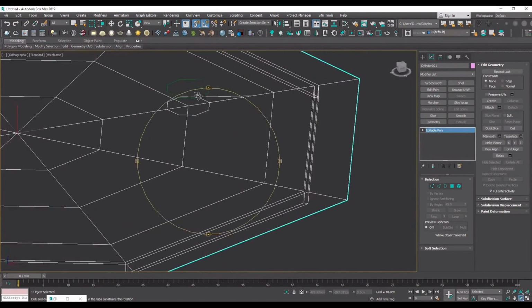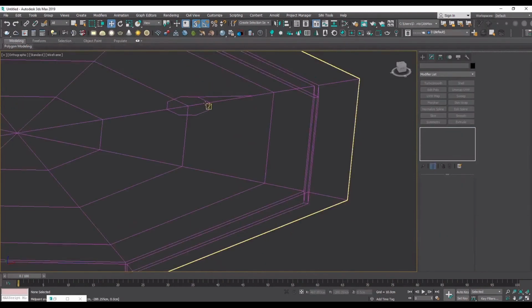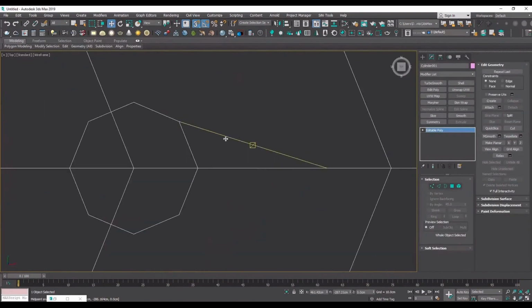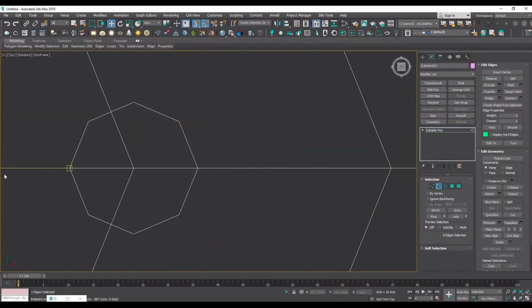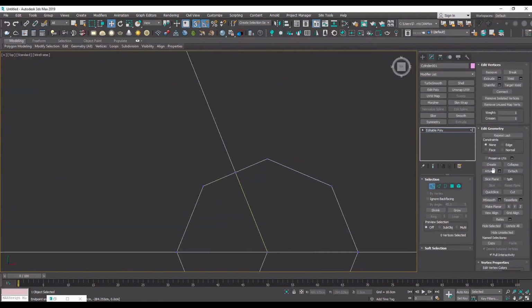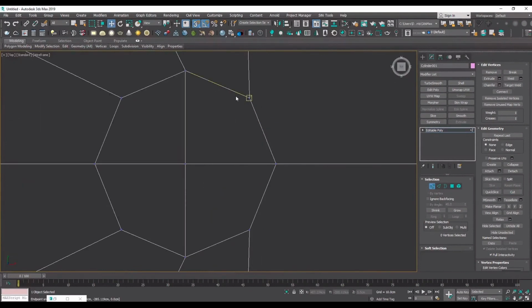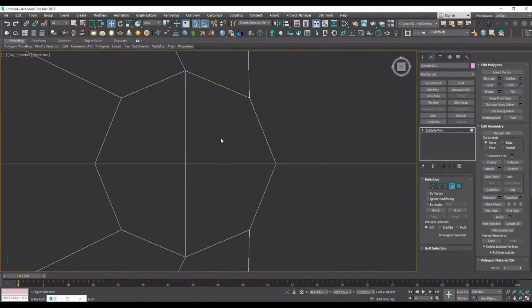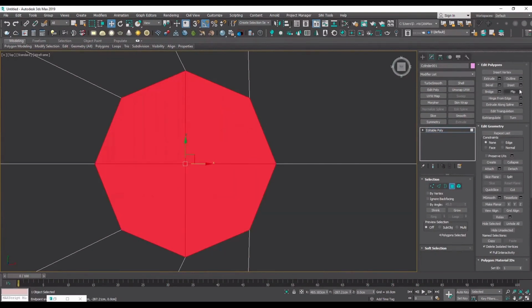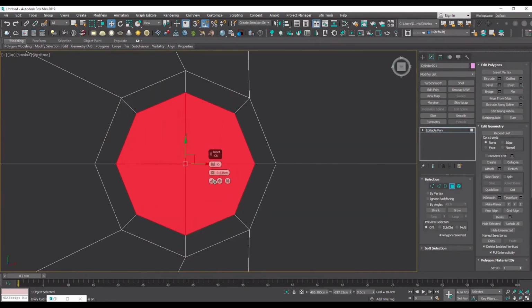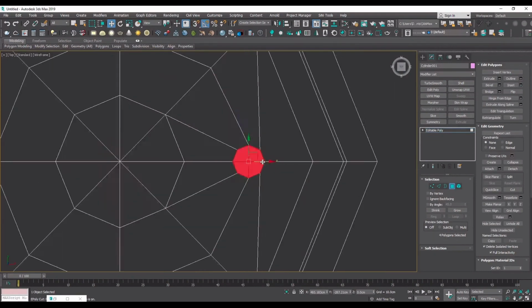Okay, I think we're good now. The thing we have to do here is to remove first this extra edge, and then by using weld operation, add some edges to the right positions and not let any vertices float without connection. It's so important. Remember, when I said consider the n-gon a little bit bigger, it was because we are going to inset from it one time and secure this area. Now, to be more clear, I'll show you what happens if we don't do that in just a second.